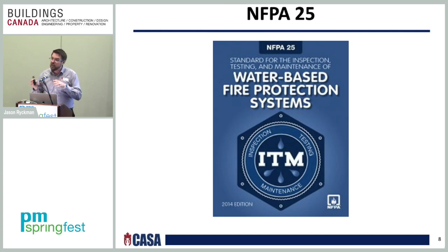One thing you can't get confused with is the use, whenever you are inspecting, testing, and maintaining, of the installation standard as well as NFPA 25. The only time that you use the installation standard is whenever you have any renovations, additions, or any deficiencies that have to be repaired for some reason. That ultimately would fall under the installation standard and not the NFPA 25 standard, which is the inspection, testing, and maintenance document.